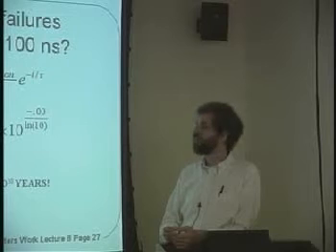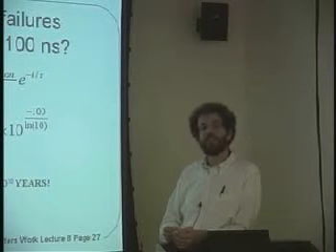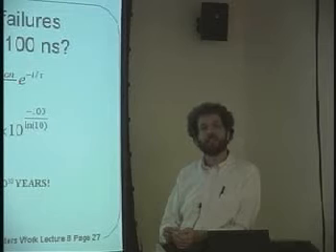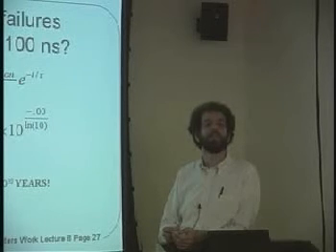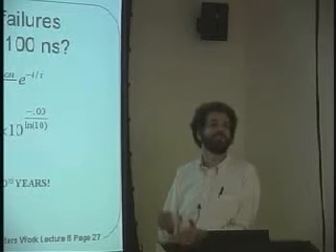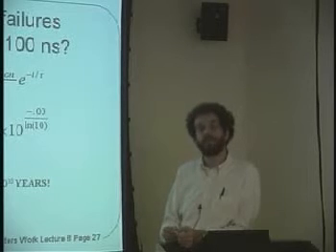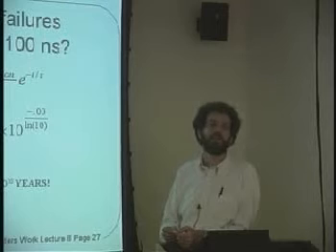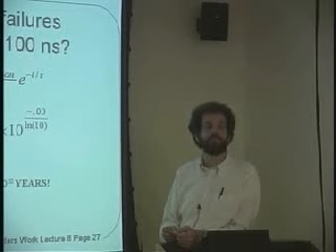well. But if you're not going to obey the setup and hold time, here's what you can depend on. You can't depend on the flip-flop giving you the answer in the propagation time of the flip-flop, which is typically 2 nanoseconds. What will happen is if you violate the setup and hold time, it'll take longer to make up its mind, and the answer may be random.